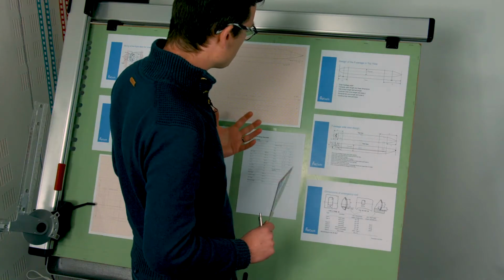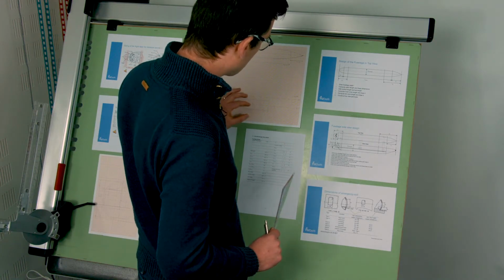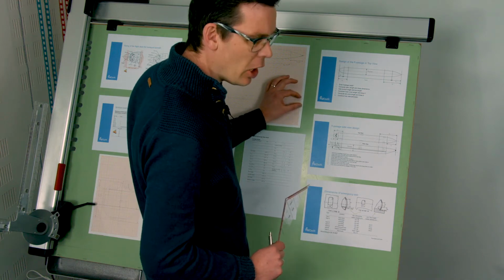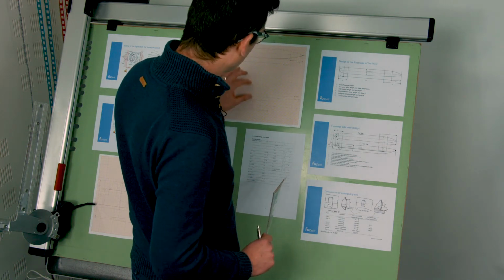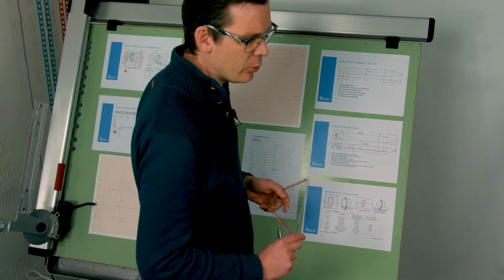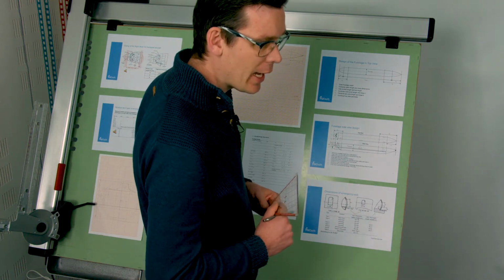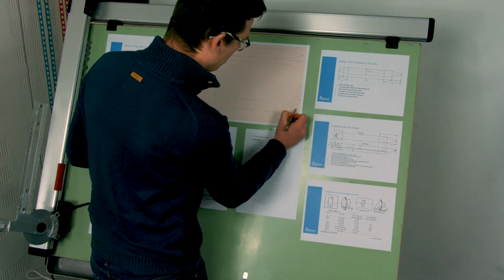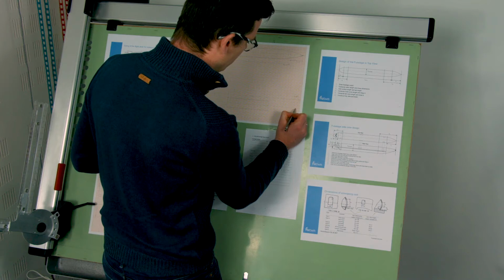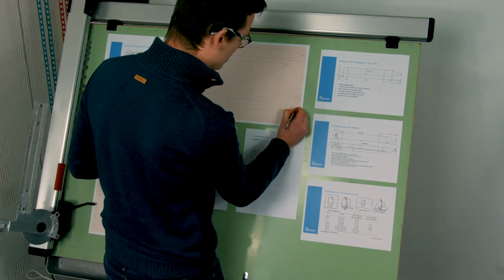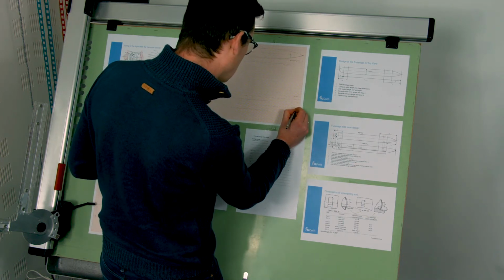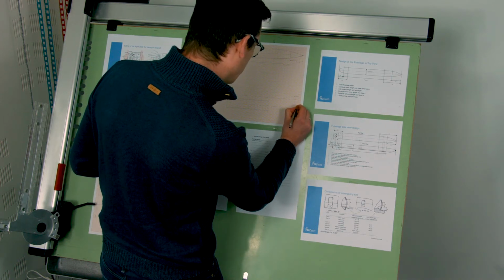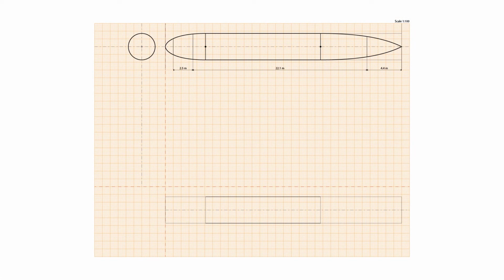So for that reason, I'm already in this part of the design taking into account a little bit of upsweep of the fuselage. The symmetric design would be the design which would have the least amount of drag. So that would, from an aerodynamic point of view, be the most beneficial. So rather than deciding to use the point on the center line as the rear part of the fuselage, I'm deciding to move that up about 80 centimeters here and use that as a notional point.